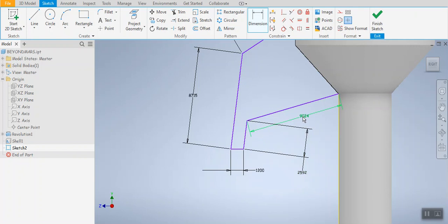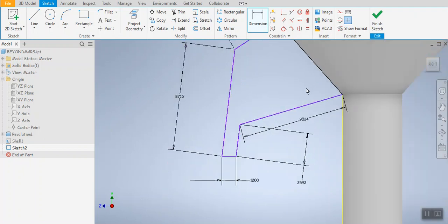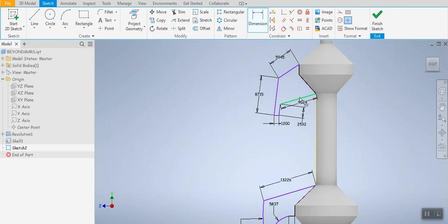I'm not supposed to say this to you because this last number may not be exact, but you make sure that the end of your line joins to the first point of the line, and then it is one closed polyline that we can extrude.